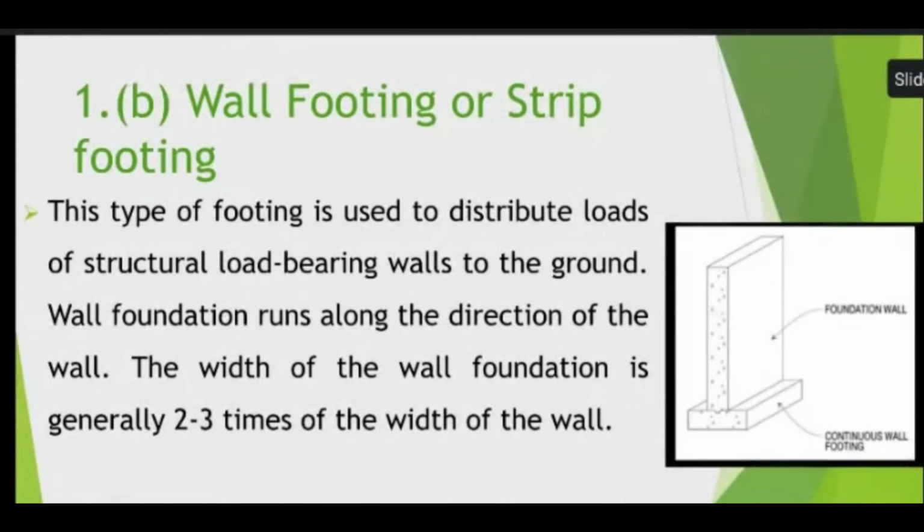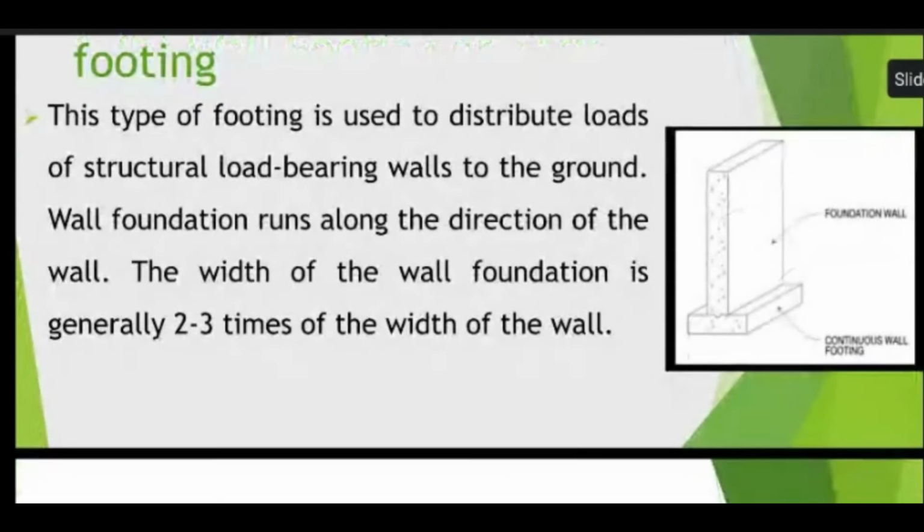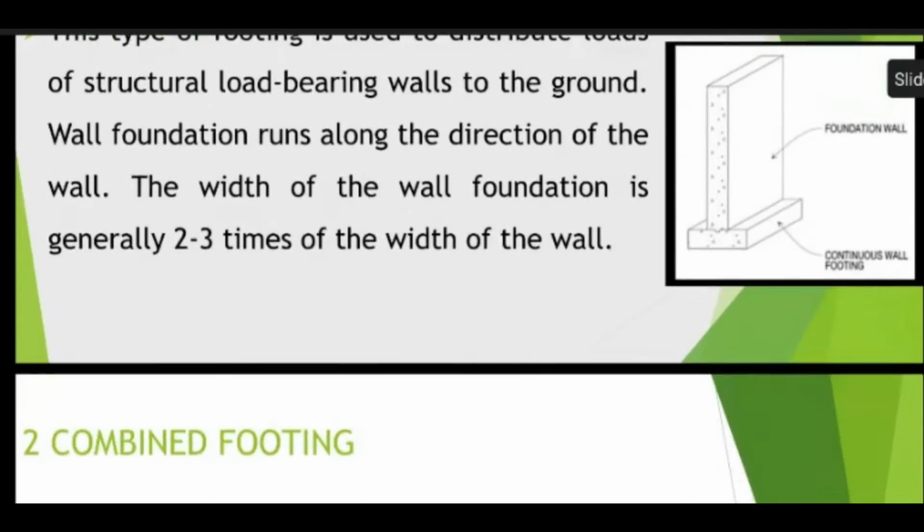Second, wall footing or strip footing. This type of footing is used to distribute loads of structural load bearing walls to the ground. Wall foundation runs along the direction of the wall. The width of the wall foundation is generally 2-3 times the width of the wall.